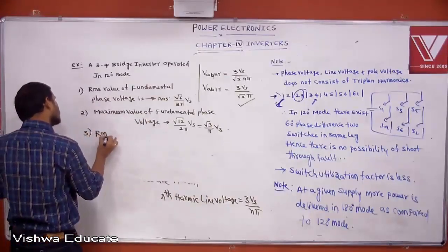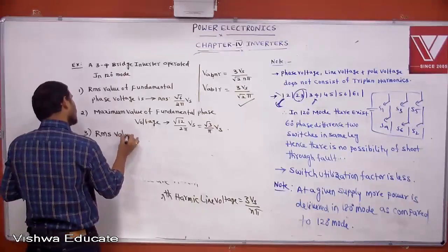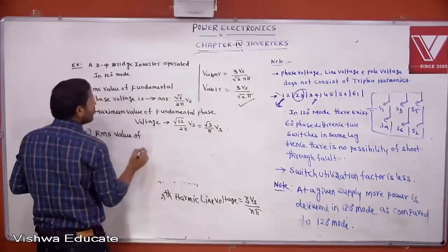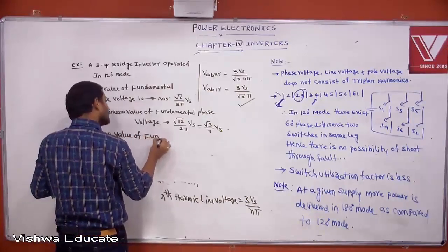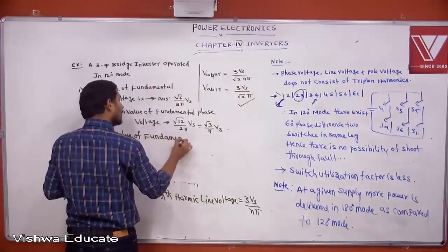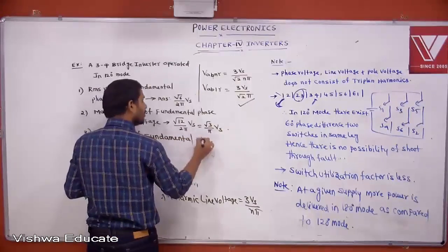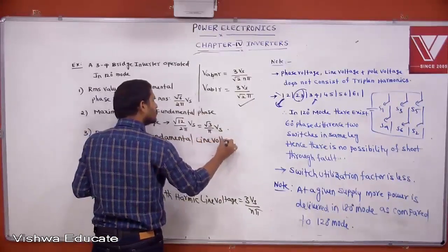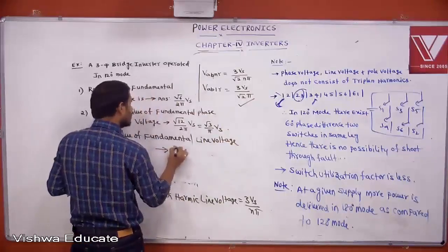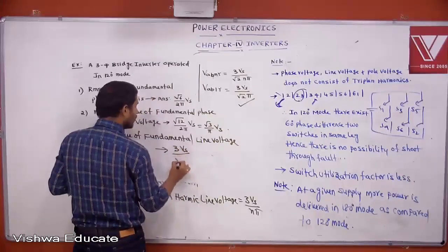Yes. If it is asked like this: RMS value of fundamental line voltage. How much you tell me? Yes. 3Vs/√2π.